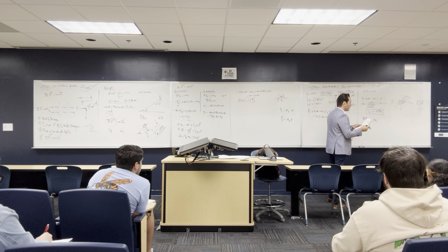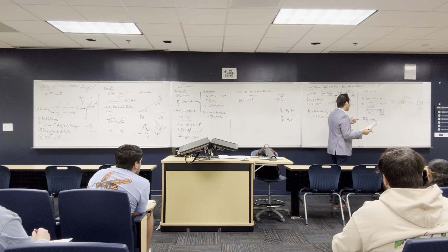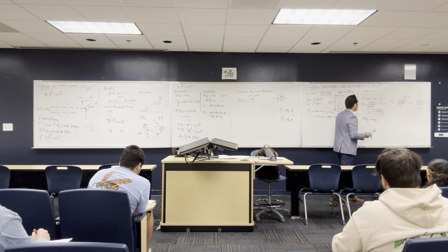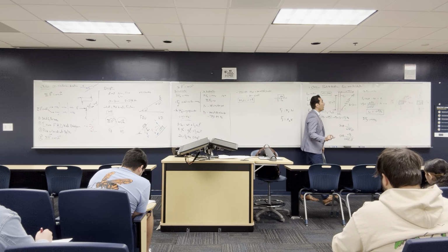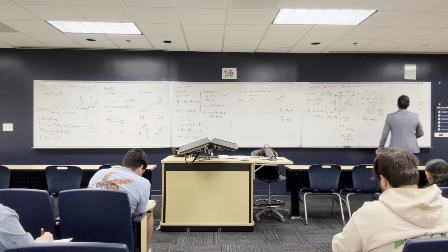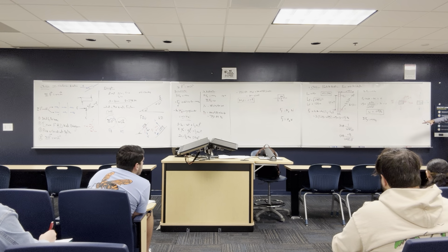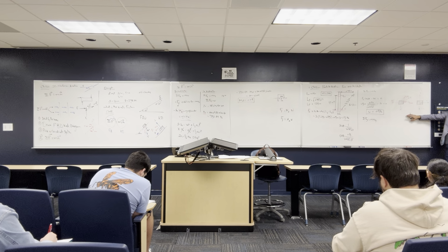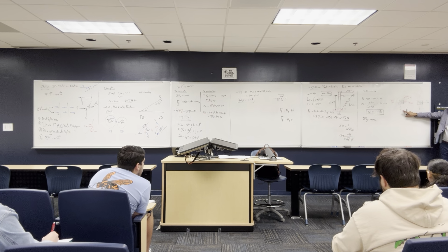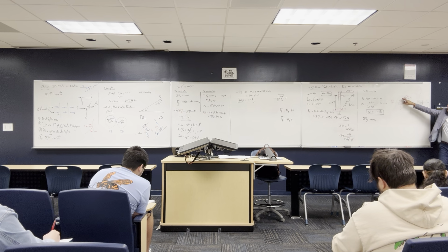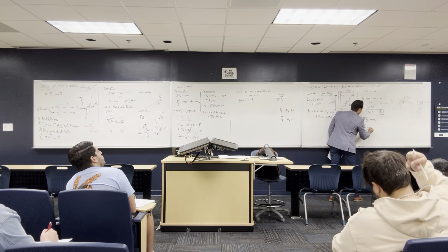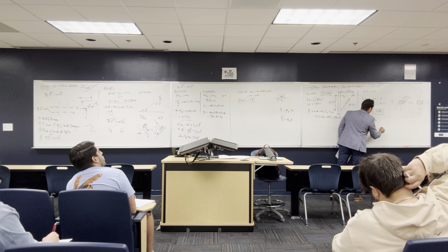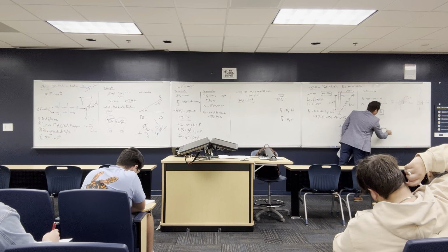In this problem, I'm asking you to determine the y acceleration and the normal force. I got the normal force. In the second, I want to get a_y. So what are the forces in the y direction? And pay attention to the positive or the negative. Weight: is it positive or negative? And Fs sine theta, is it positive or negative? Positive. So I have Fs sine theta minus W equal to m a_y.